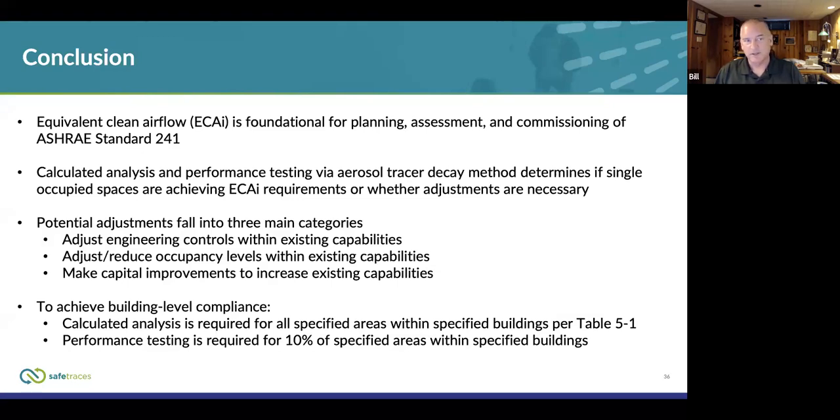I think the issue that needs to be detailed more is scaling from these tests, which have to be in at least an 800 cubic foot chamber, to spaces of arbitrary size. That's not something that we're working on, but it's a known issue. And I think that you could do an engineered solution and probably persuade an authority having jurisdiction that it was a reasonable value if it was something that's currently a gap in the standard, like upper room UV.